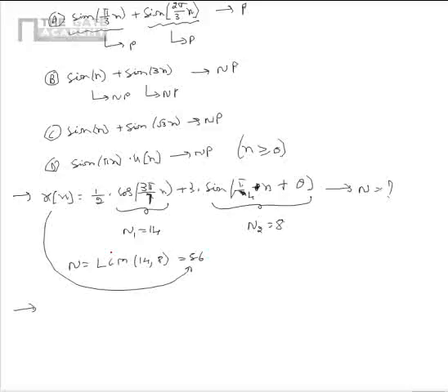Now let us consider another signal which is given as x of n is equal to 6, 2j, 4, minus 4j, 10, where the value 4 corresponds to the instant n equal to 0. Now we have to find the conjugate symmetric part of the signal, xe of n.